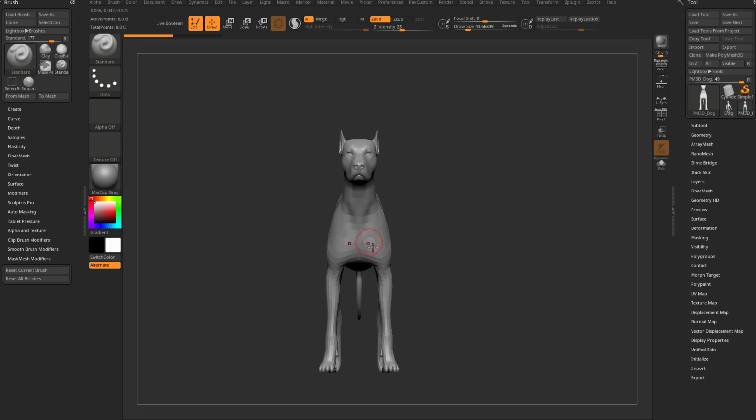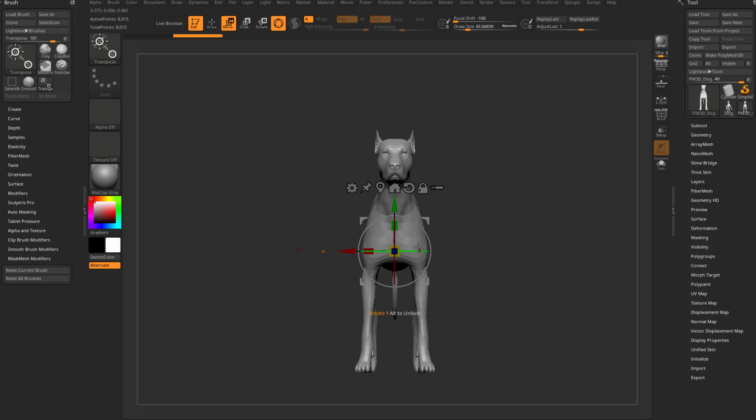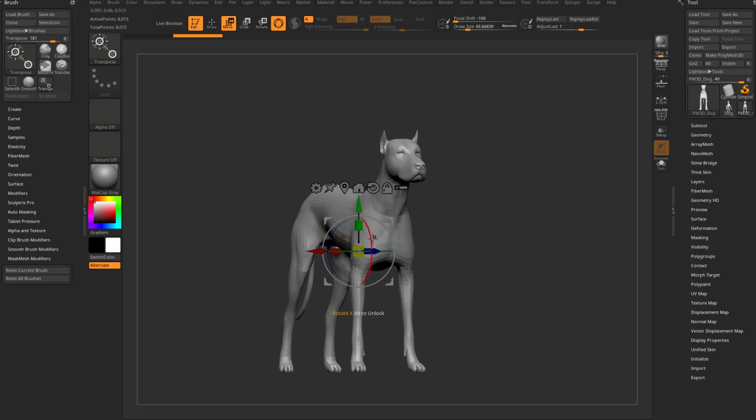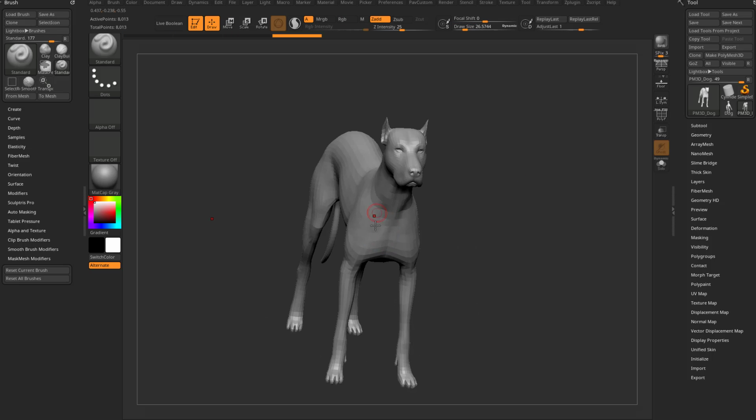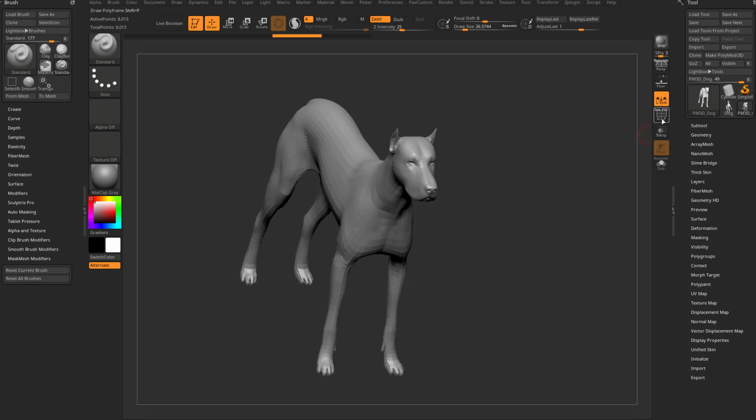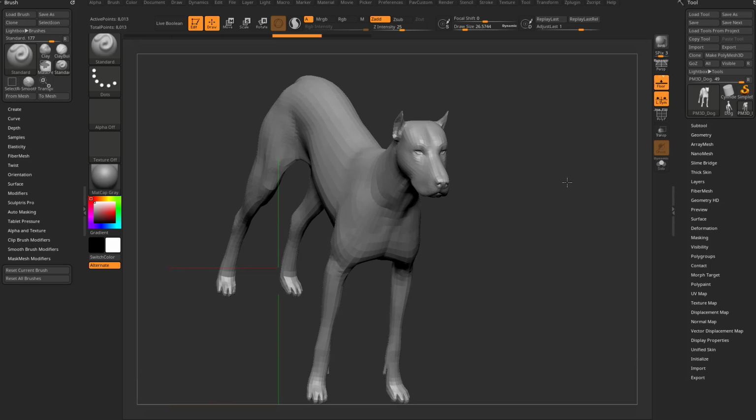Of course, we're across the world axis now. So if I was to go in here and hit W to go into Gizmo so I can move this dog over, and let's rotate this in space and just kind of move it over here. Again, I have X symmetry turned on, but I'm not sculpting symmetrically, so I'm going to turn on local symmetry. In versions of ZBrush 2022 and before, the fact that my dog is just kind of pointed down in space would break symmetry.